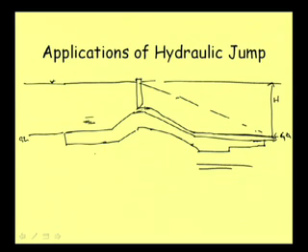due to uplift pressure. Now, when water is percolating through the ground, it is moving this way. Okay. Now, as the water is percolating, there will be seepage pressure, and otherwise also, when this is not impervious, I mean there is a communication, there will be uplift pressure, because water is continuous through the soil also. So, water will have some uplift pressure at this point.